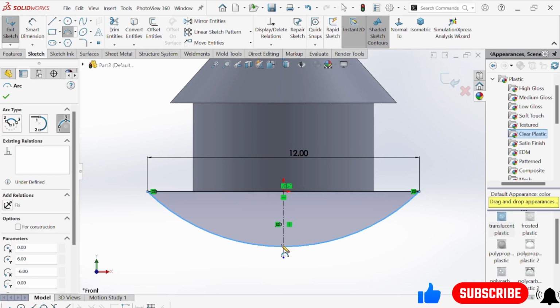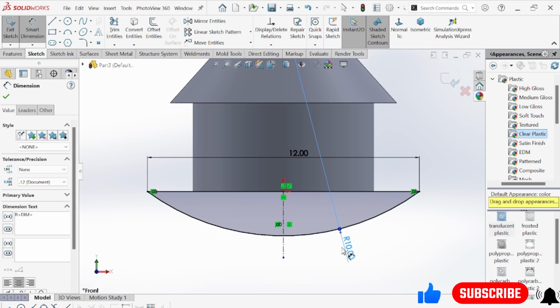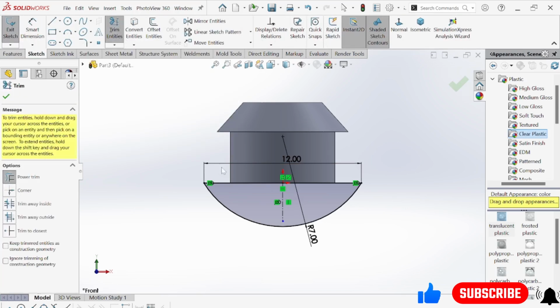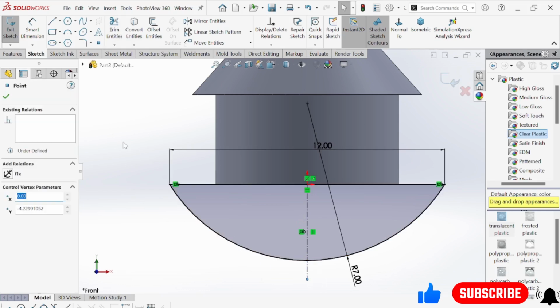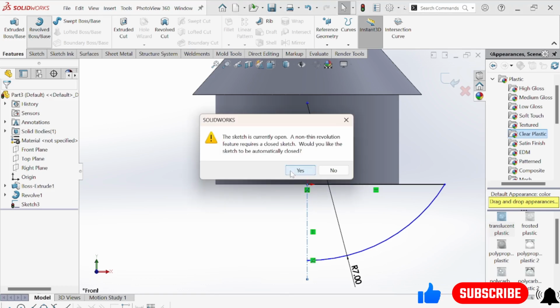Now, let me tell you what you have to do. You just come here and give it a radius. Let's make this one 10. 10 looks fine. Actually, not 10, let's make this one 7. 7 looks very fine. Simply go to feature and trim this one. But right now, let's make this arc a little bit bigger. We just need half of it because we are going to revolve this. Go to feature, go to revolve boss base, and again make this one okay.